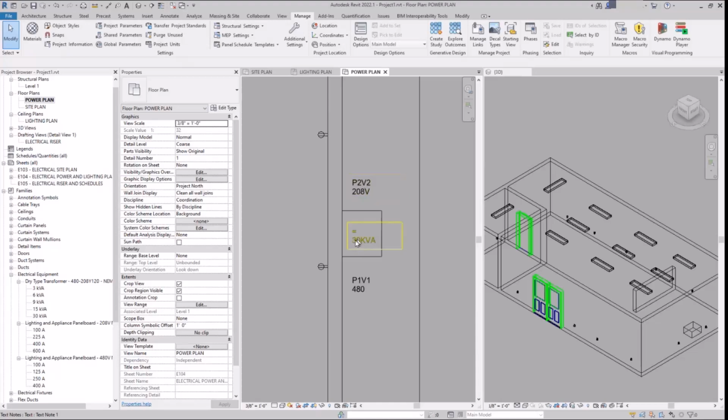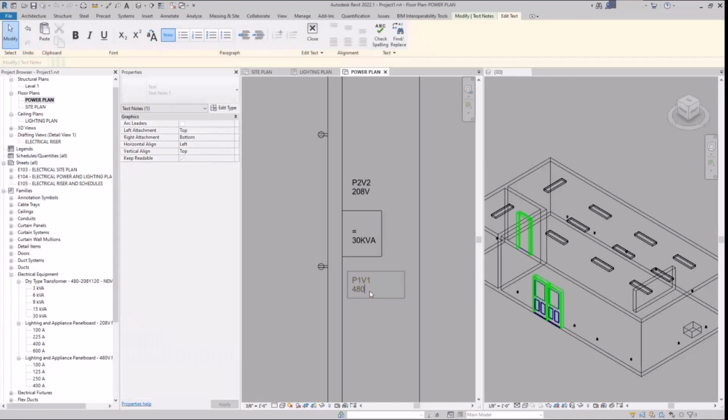Well, if I know that transition point, that what is the driving factor of this electrical equation is 30 kVA, and I know I've got 480 volts on this side, that gives me, what was it, 36 amps? Yeah. 36 amps, right? And on here, if I got 208 volts, that gives me 83 amps.